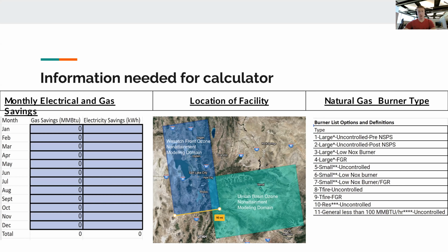For example, let's say you're working with an air conditioning unit. I would probably make an assumption that during November through March, it's not on, and then from March through October, it is on. Then I would normalize the total energy savings using the average high temperature of the remaining months that we're assuming it does run.